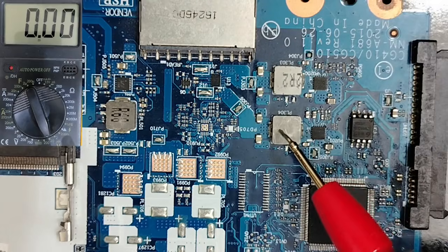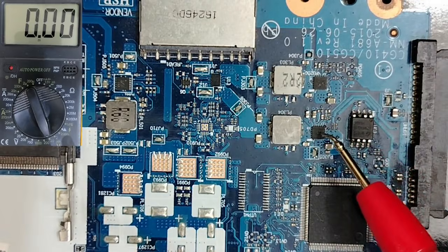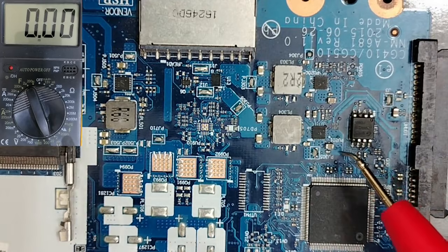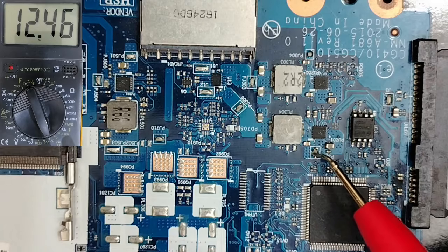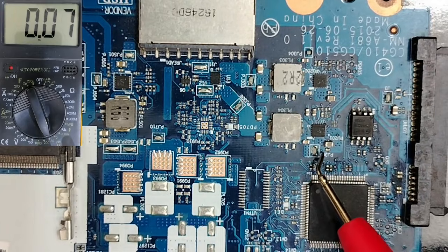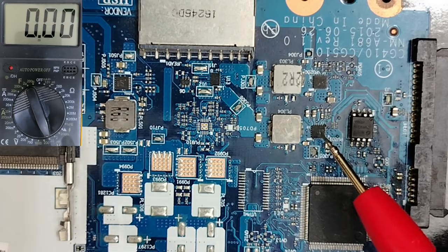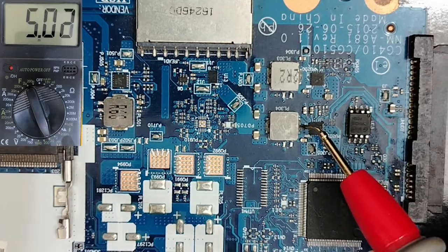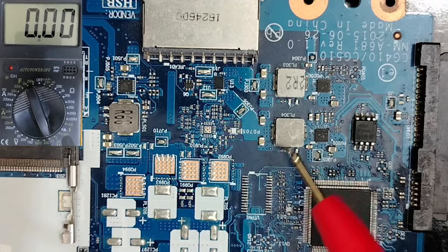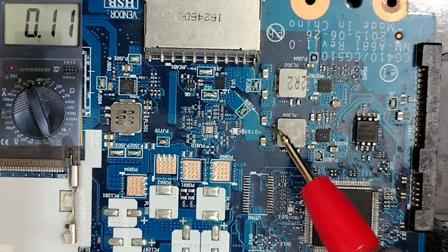So guys, for this circuit, we don't have MOSFETs. We have controller ICs. One IC for this channel and a second IC for this channel. So for this channel, for example the 5V channel, we have this IC, and over here we have the input. If we check here, we have 19 volt, as you can see. This is basically the part. Here we have the input. And here we have ceramic capacitors, input capacitors, where we have 19 volt. So we have the IC here, and we have the inductor where we can check 5 volt, and we have 4 ceramic capacitors. Pay attention. And we have the output here. We have, as you can see, 2 big ceramic capacitors, which means here we have the output.